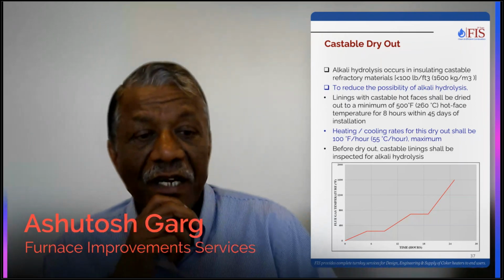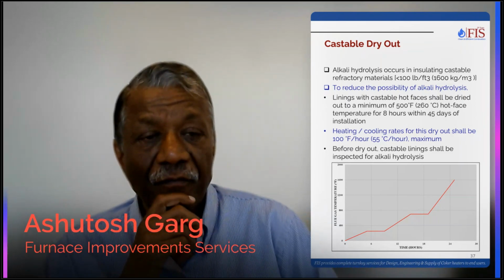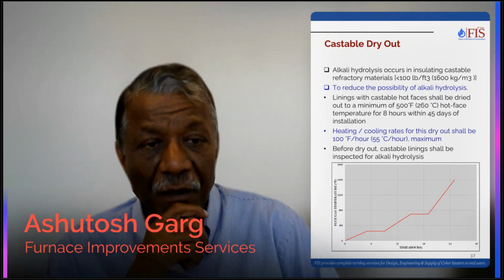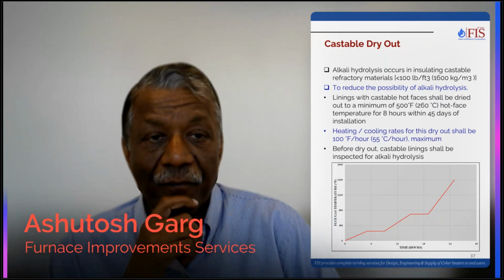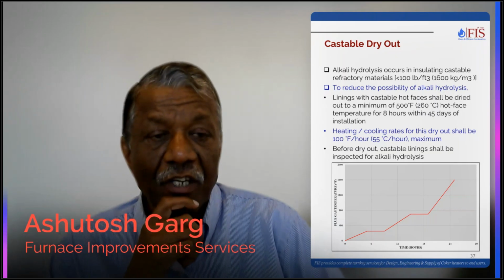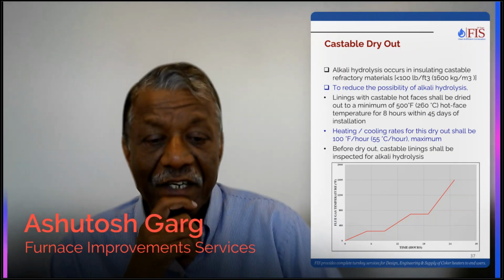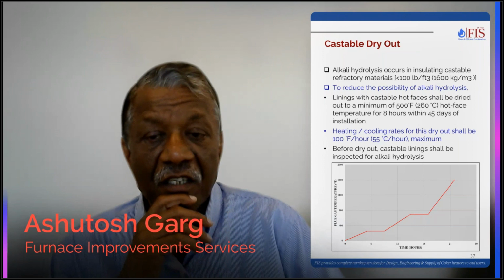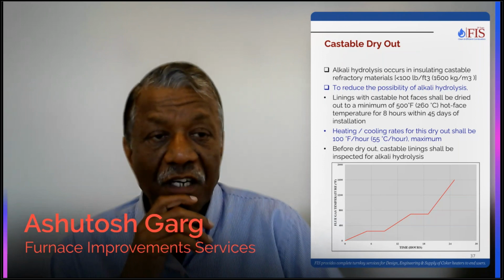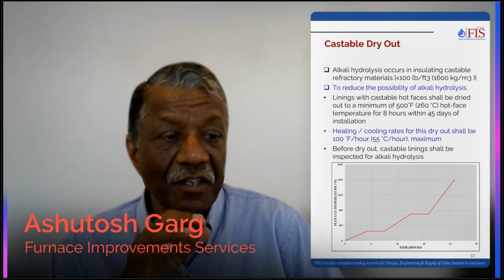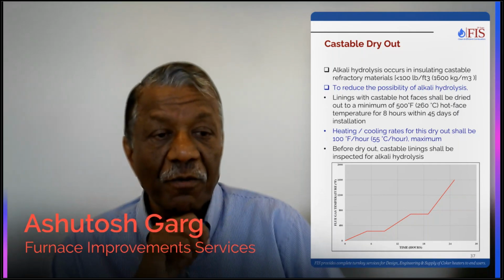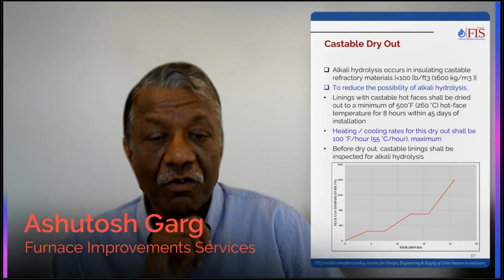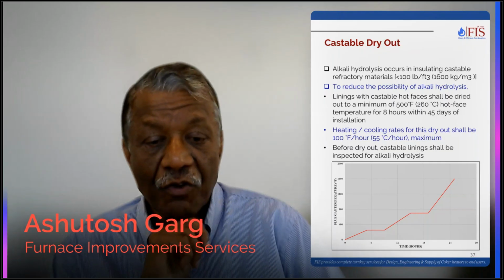So we do that in the shop very often, and there are a lot of companies who specialize in this type of work only. So shop dry out has become almost like an industry standard for making sure that we don't develop alkali hydrolysis, because there are cases where the heater is sitting in the field for 2 years because the project got delayed. So you don't want to ruin the castable lining.